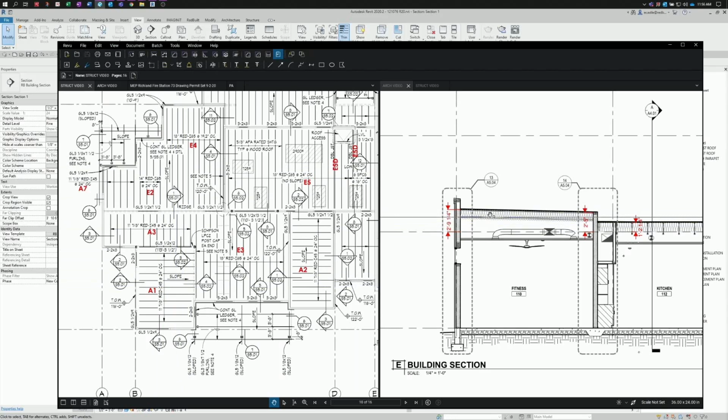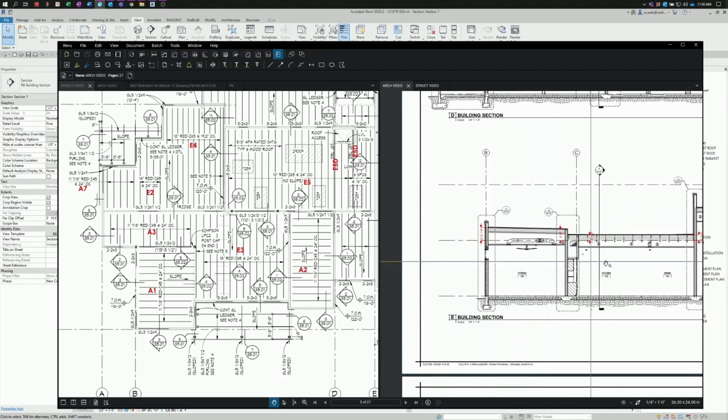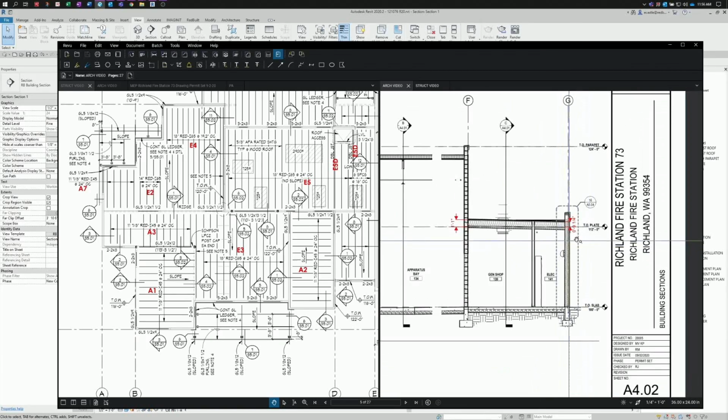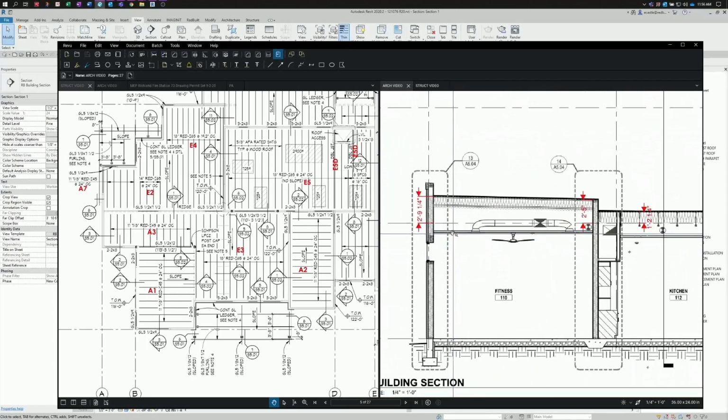From the view over here, this is the plane that we're going to be creating, and the only way I was able to determine was scaling the drawing. So I have 2'9" from our top plate that we found before. And then with that and a 1/4 inch slope, we'll be able to create our work plane.